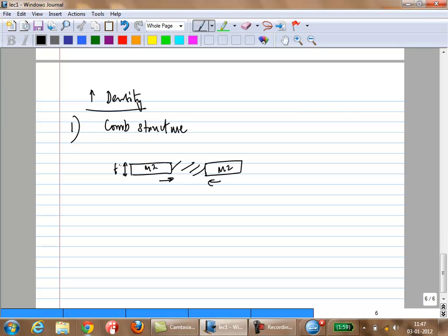So you can do both of these. You can do one of these, and then you can also get metal layer to metal layer capacitance also. You can do both of these. So one way to increase this, obviously you're interested in sidewall area between 2 metals. For a given area, you're interested in the sidewall area between these 2 metal lines.